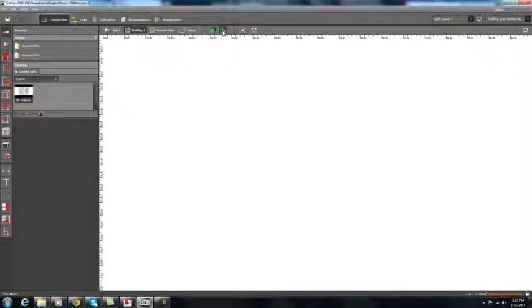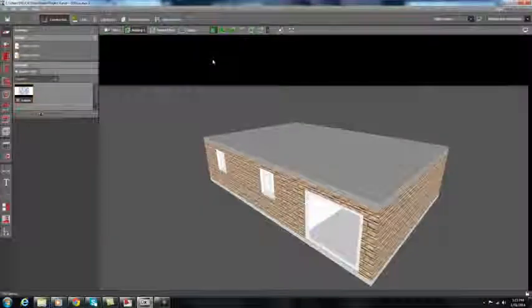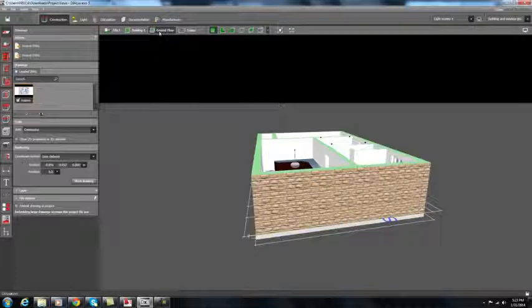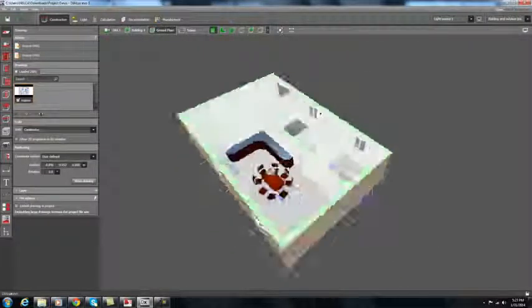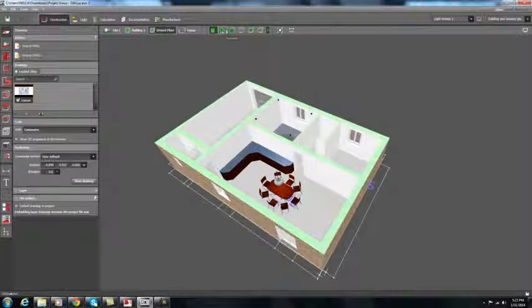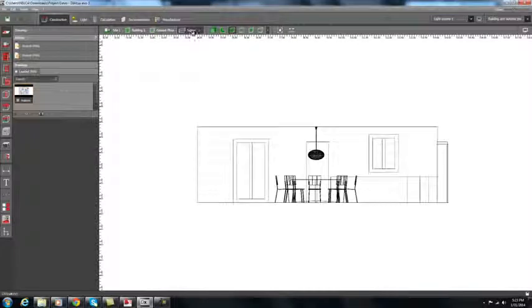Similar to the site, you will have the floor plan, and then the 4 elevations. And then if you go to the ground floor tab, you will see that ground floor plan, and of course you also have an option for the plan view and elevations or sections. You also have these room tabs, in the pull down menu, there's an arrow here.